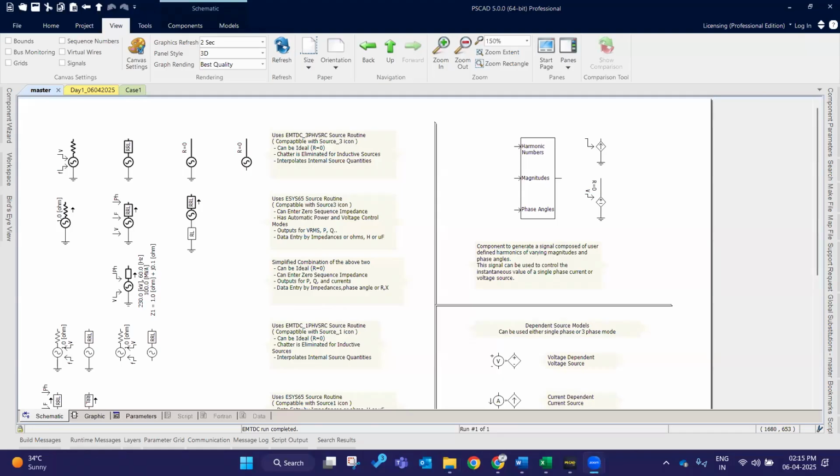That is simple. And why are we modeling like that? In some instances, frequency and voltage are the parameters to be controlled, right? At that time, I can use this type 2 source. Why? Because here the two parameters that can be controlled are frequency and voltage. Similarly, if you want to control frequency, voltage, and phase angle through external control, at that time you can use model 1, this one,